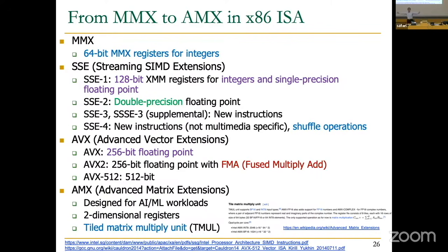Now, 512 bits is, if you're operating on 8-bit values, that's 512 divided by 8, right? That's 64 elements at a time. If you're operating on 64-bit values, still 8 elements at a time. Not bad, right? But of course, think about 512 bits now. Your memory system needs to support all of that as well.